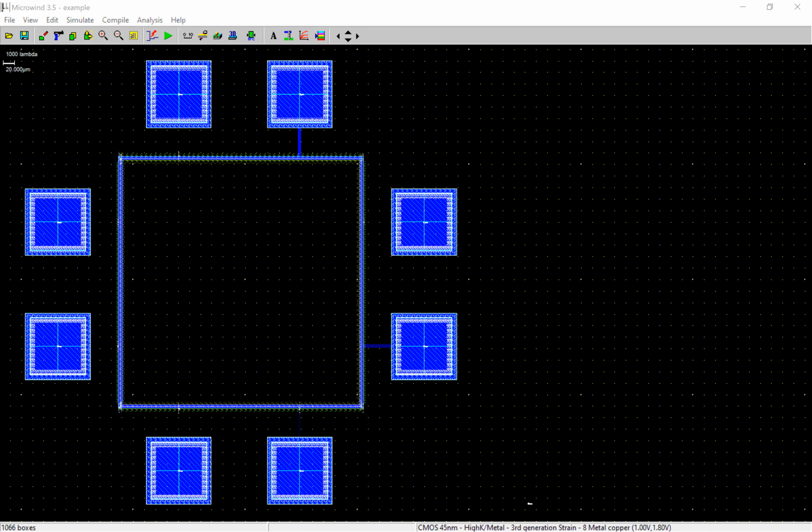So let's start. Sorry for my internet connection, it got weakened. We were trying to insert a NAND gate inside a pad ring. We can definitely reduce the size of the ring a little bit proportionately, but we cannot make it just slightly bigger than the NAND gate.